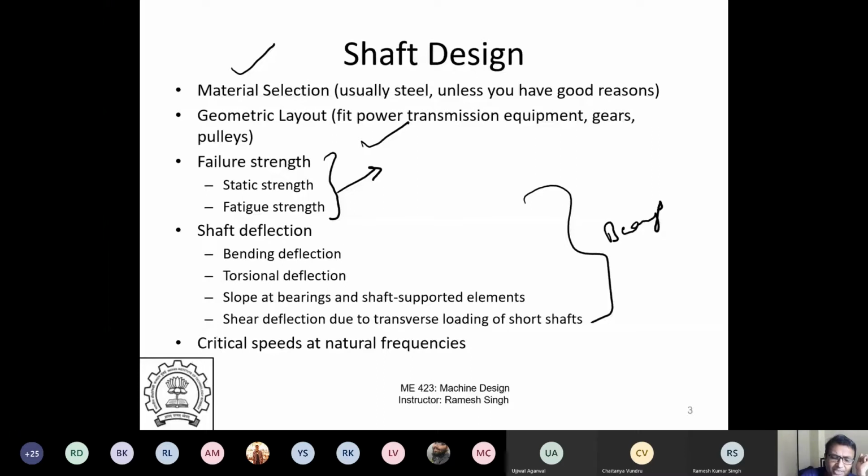And then another important concept is critical speeds and natural frequencies. So basically natural frequencies are very important, because if you run any rotating equipment at natural frequency, you run the risk of damaging the very expensive component. So as I said, the small process turbines which are there in process industries, those cost 50 crores. Imagine what planes would cost. Plane turbines can cost you a few $100 million, right?